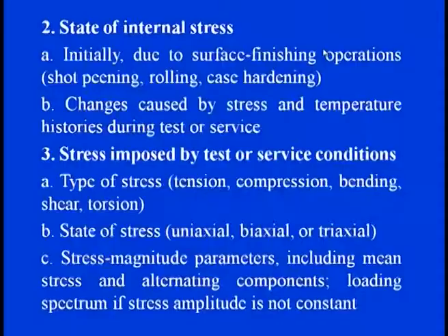When different types of cyclic or fatigue loading are there, the material properties are straightaway affected. Second, the state of stress, whether the stress is uniaxial, biaxial or triaxial as per the tensor nature of stress, or the stress magnitude parameters like the mean stress or alternating components due to the loading spectrum if the stress amplitude is not constant.